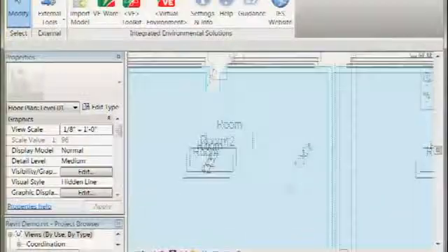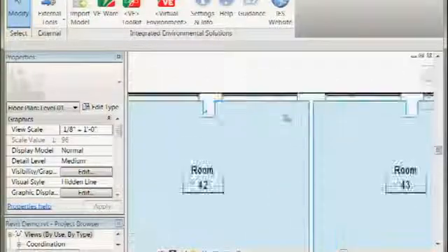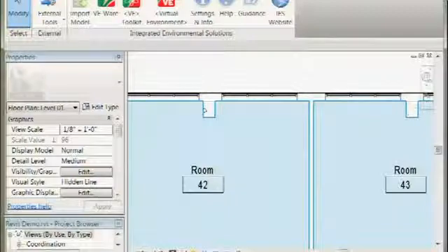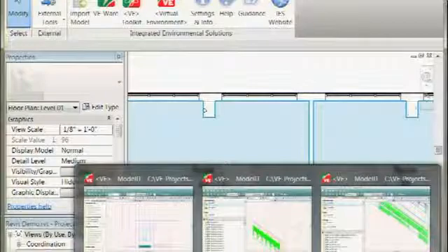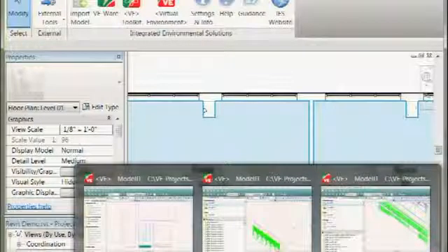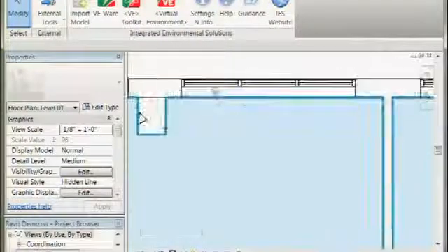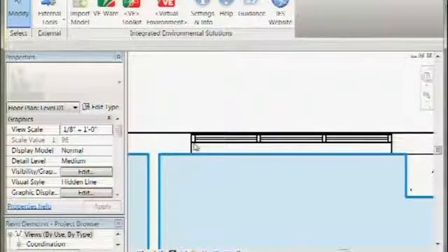It's kind of an interesting thing that happens when you bring in stuff from Revit. So inside of the virtual environment, if you're just doing thermal analysis, you're probably not going to use your inner volumes so much, or maybe standard-wise in your office you've decided to always use inner volumes. But in the virtual environment, you always have inner volumes defined. So even with Revit models, only with Revit. When you bring it in from SketchUp and you do a thin-walled model, your inner volumes are not defined.